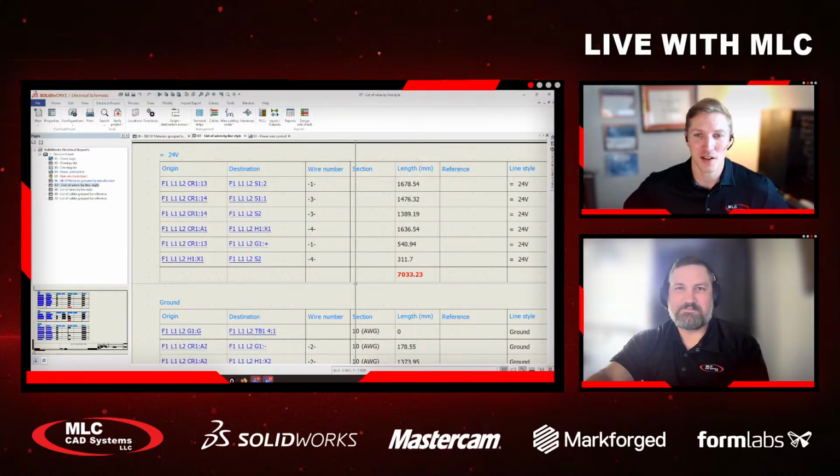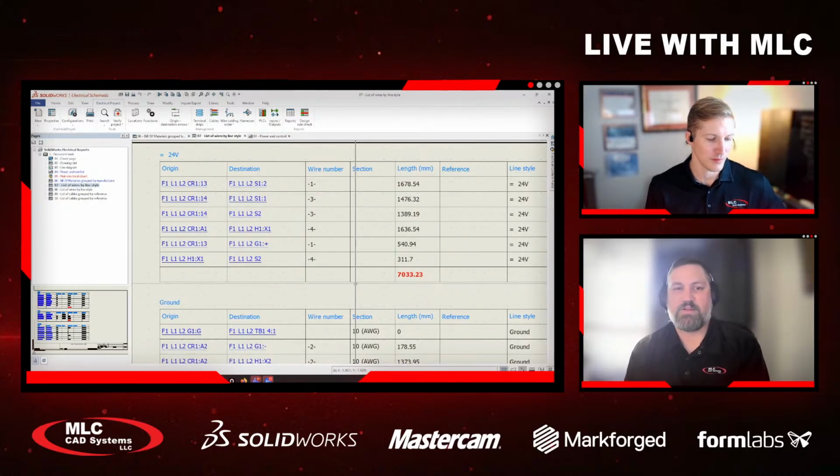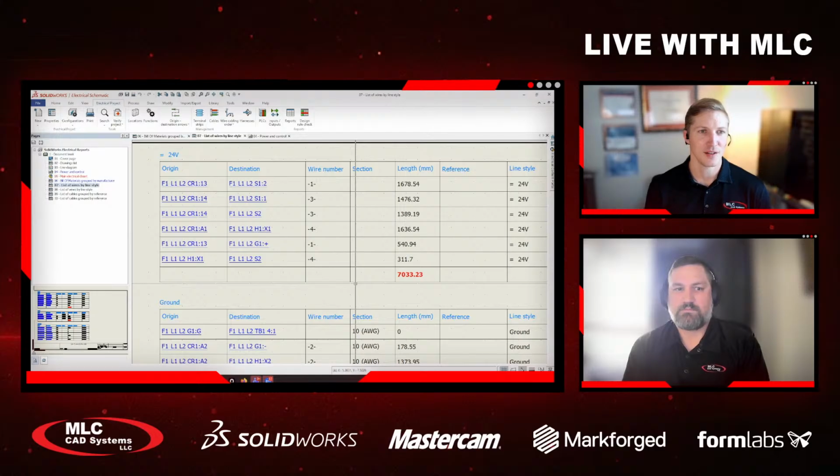And I mean, I've seen it on the 3D side, that's one of the things that I'll show off when I'm working on the routing side, the mechanical side of things, is that you can move something, rebuild, and see these lengths change immediately. So that's the information that's getting fed back. Everything else here basically comes from the 2D side except for the length, huh? That's correct. And whenever you move something in 3D, just move it and then rebuild, let it move, and then you'll have to come back here and update this report because remember, it's a snapshot in time. Yeah. Dude, that's awesome.